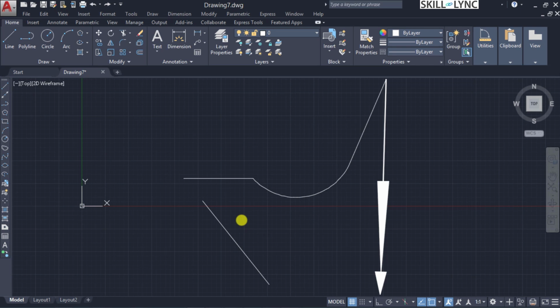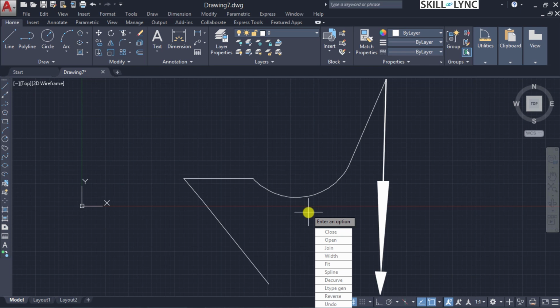So we'll go to the PEDIT command and select multiple again, and select these two by the crossing fence option. Now again, the option to convert to polyline, yes, go to join, and now the join type as add, and say a fuzz distance of 50. In that case, as they are coincident, it directly joins the segment.